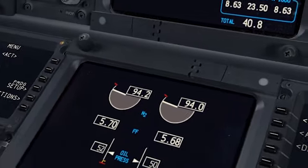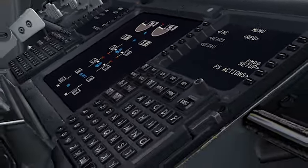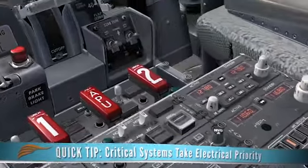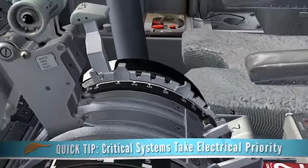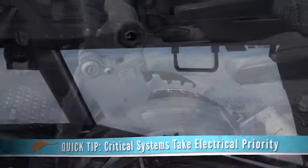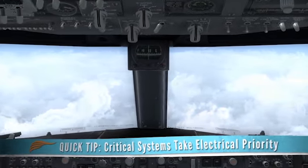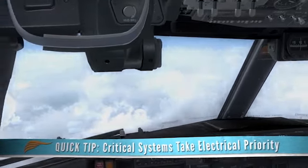The whole purpose of buses is to allow essential items to still remain powered if there was an electric power shortage or emergency. During an electrical emergency, it is far more important to have an active, functional communication radio as opposed to having functional strobe lights. For this purpose, both items draw current from different electrical buses.